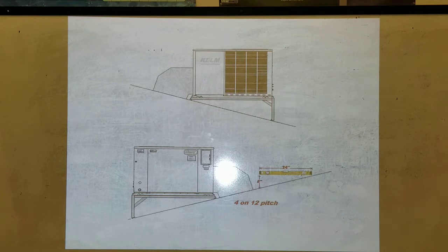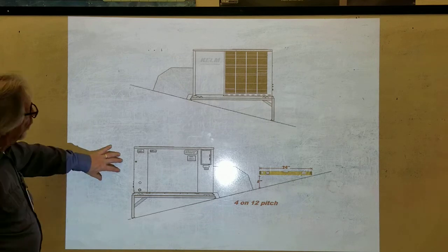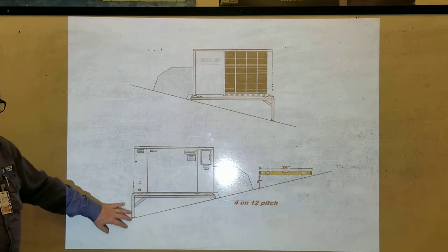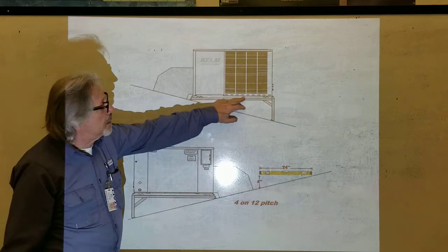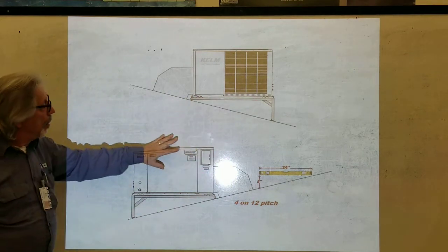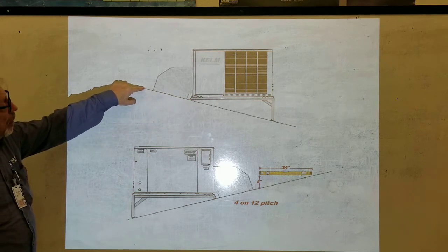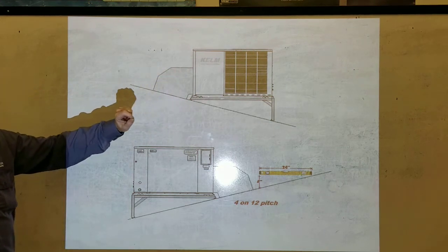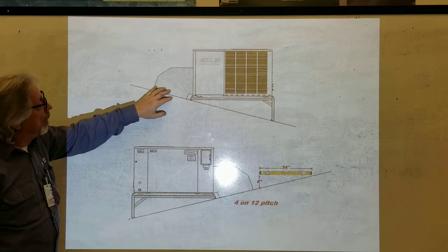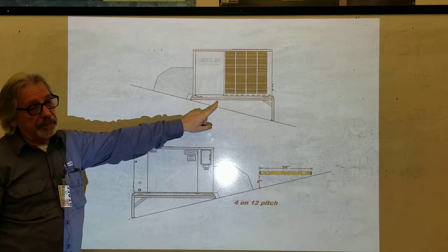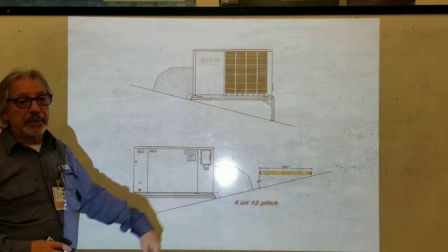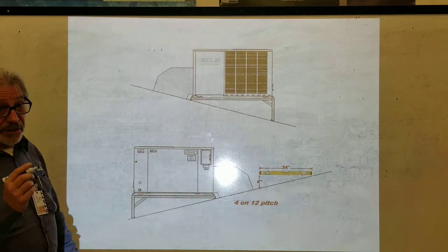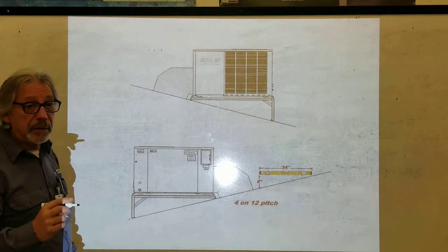Roof pitch. So you got a typical rooftop unit on a pitched roof, right? So knowing how to get the pitch matters, because if you're gonna replace this stand with a new unit, or if you're gonna make the elbow, you're gonna give the information to the sheet metal guy, or if you're gonna do it yourself, you're gonna need to know what that pitch is. So in order to get the pitch, you need a level. This is simple stuff. Do you have one of those here?